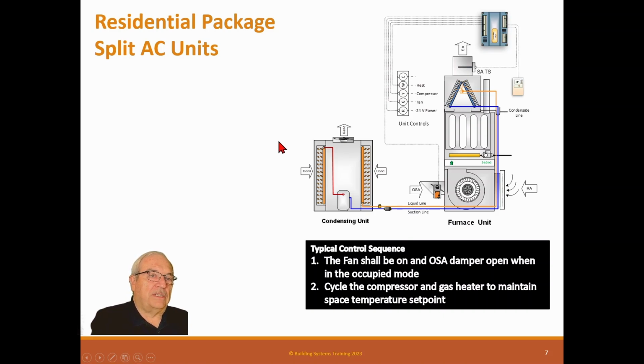So that's basically a split system. The only difference, of course, is these have to be built up in the field. So you install this, and then you have to evacuate this refrigerant line because you've constructed it, and you suck all the air out of it, and then you basically put gas in it. Or a lot of times these will be shipped with enough gas in the condenser to do that, but we have to release the gas. And then you have to test it to make sure you have the right charge. In a regular package unit, you don't have to do that. The package units come charged from the factory.